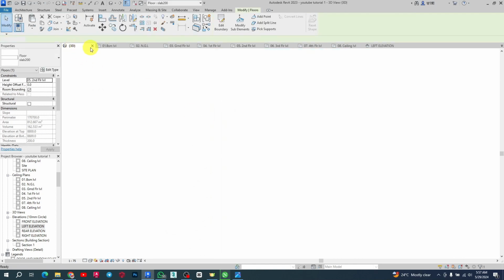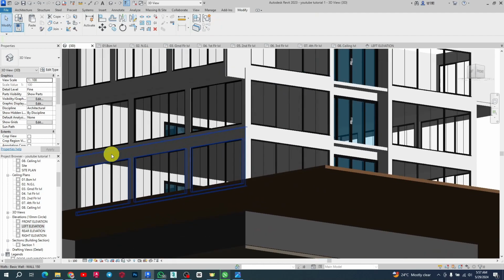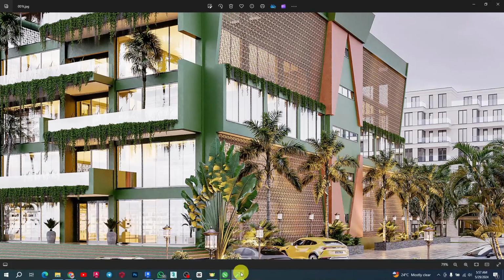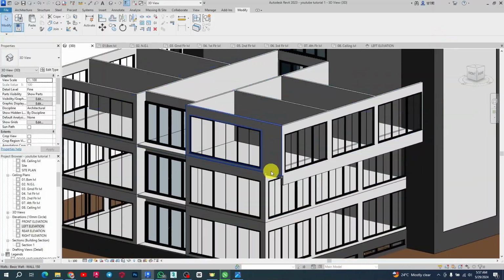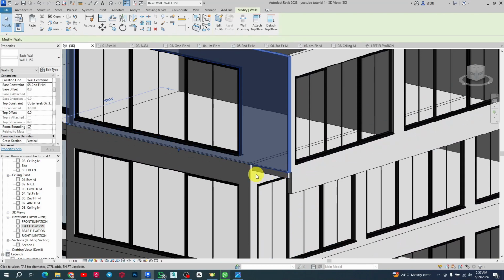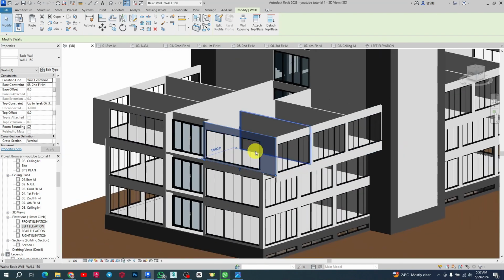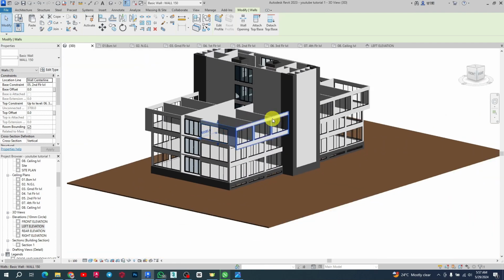Don't attach, right? I don't want to attach it. If you attach, it's going to cut the wall. So that is it, you have it there, and this one will automatically work like this position that we have here. But remember, we modified it and increased the extension, right? So go ahead and cut your own and then drop down the beam, the base. Okay, split it and drop down the base to 700 or to what will work for you.